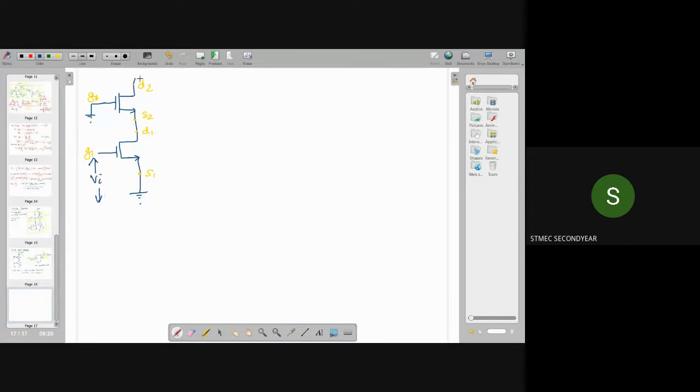Okay, now, first aim is to calculate gm. So for that we are connecting our D2, the drain terminal, to ground, and we are assuming a current I0 here. I0 will be equal to gm into V. Now in order to calculate gm, consider the small signal equivalent model of this circuit.